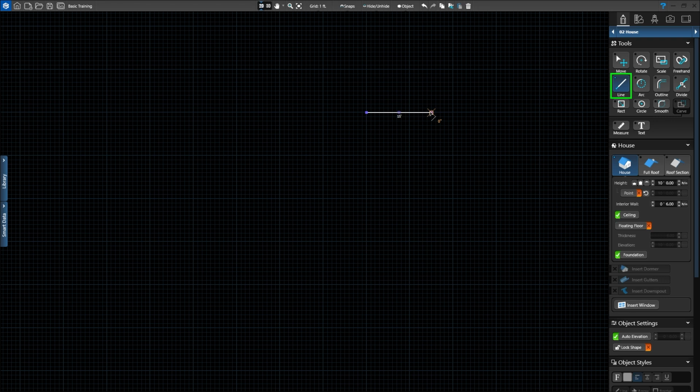As you can see, our cursor is still followed by a line, allowing us to draw the next segment. We'll draw down 53 feet and left-click again. Using this method, we'll draw the entire house. You can pause this video at any time to plot the dimensions. To finish the house, draw left 14 feet and click. Then down 4 feet and click.